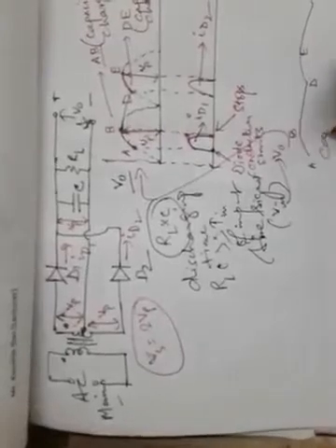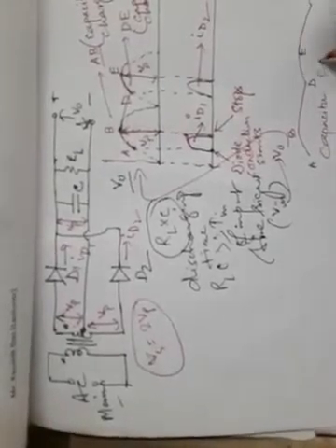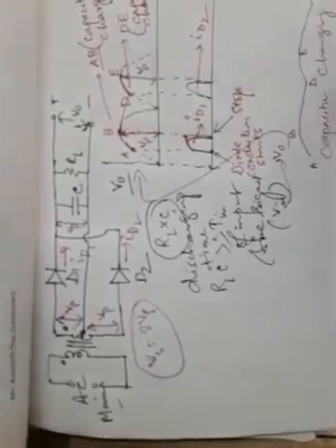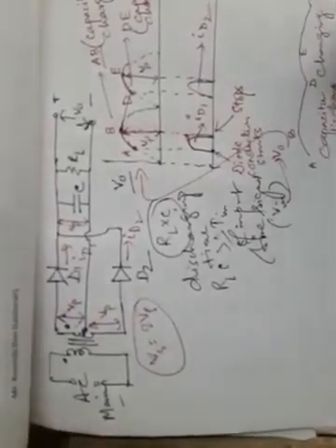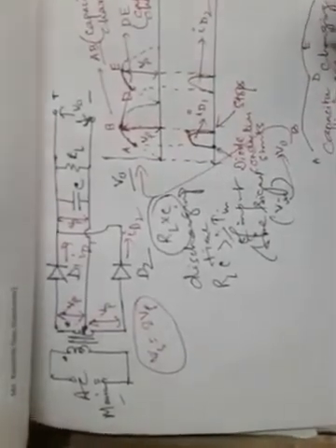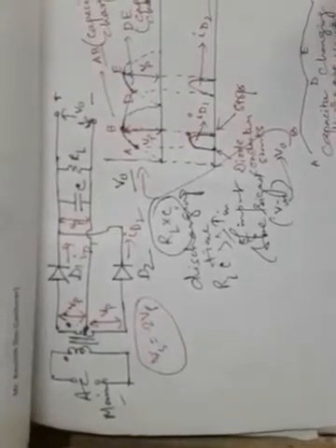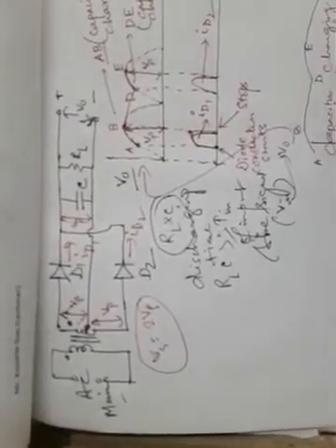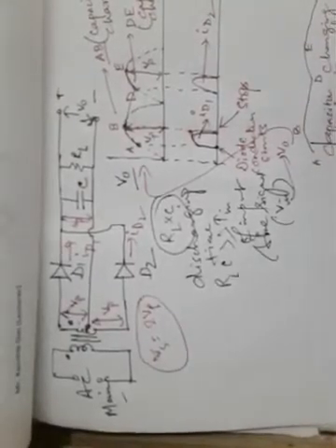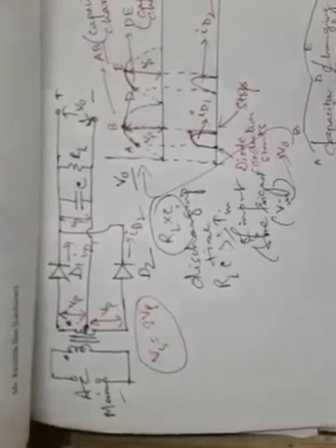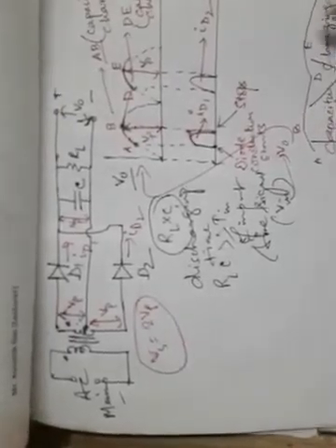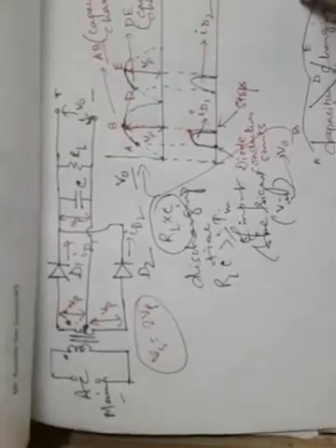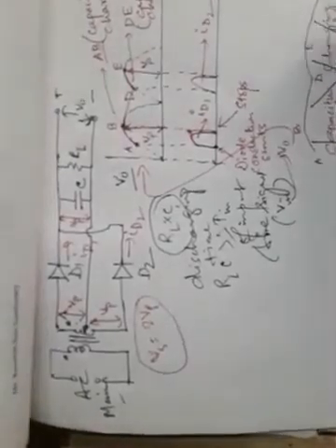So this is the capacitor charging discharging waveform, where we can say this AB portion is an indication of charging along with D, and this BD portion and this E, and suppose if this is considered as F, this BD and EF portion is an indicator of discharging of the capacitor.